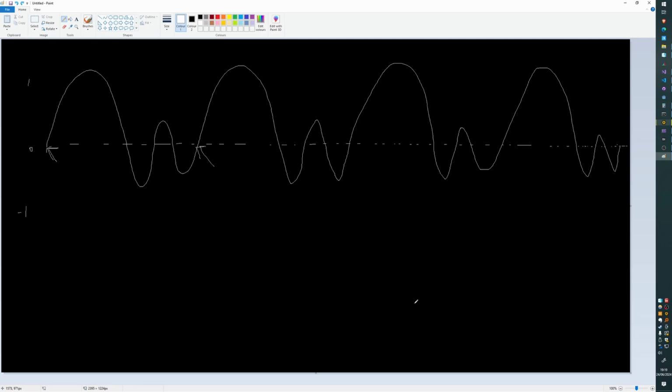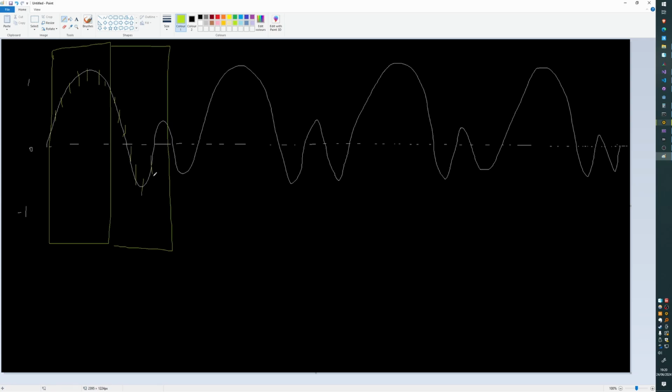So there's this thing called autocorrelation, which if you look it up online, the way people will describe it is what we're going to do is we're going to separate the signal into these windows, again, like we did with the DC bias thing. In fact, it's just two windows like this. And then we're going to go like at regular intervals or even frame by frame, we're going to compare this value with this value. And then we're going to compare this value with this value. And then compare this value with this value. And this value with this value. And continue all the way through the entire